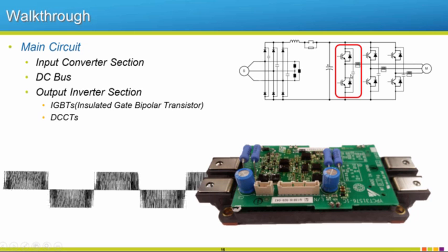We also have this section here. Those are snubber capacitors for our IGBTs. IGBTs are similar to MOSFETs, except a MOSFET's really for low voltage, really high switching frequencies. An IGBT is for higher voltages and quite a bit lower switching frequencies. Still fast, not anything like the old days, but they're getting faster and faster too. So look for newer drives being able to run higher switching frequencies.